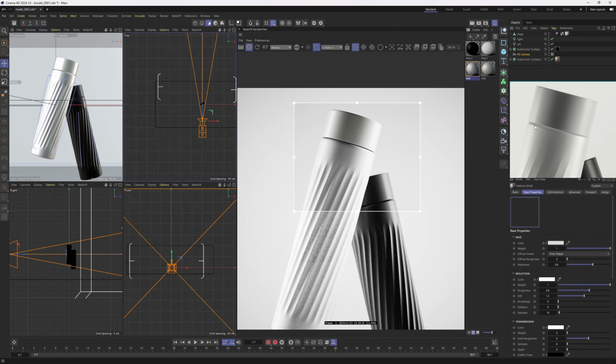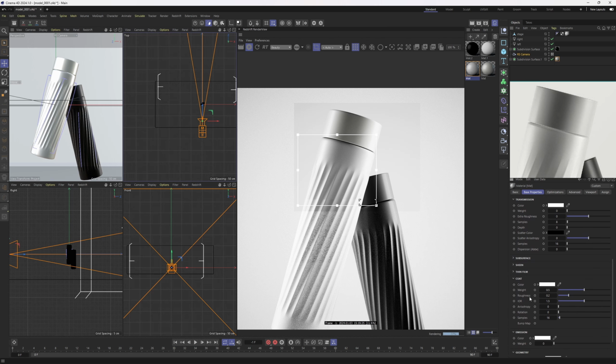I'm gonna open up that material. I'm still not happy with the material on it, so let's try to lower down the roughness of it first of all. This is gonna make it more metallic, so let's bring that down to 0.4. Okay, let's try 0.2. Yeah, we are getting there. I believe if I increase up the quad amount, I will have something similar.